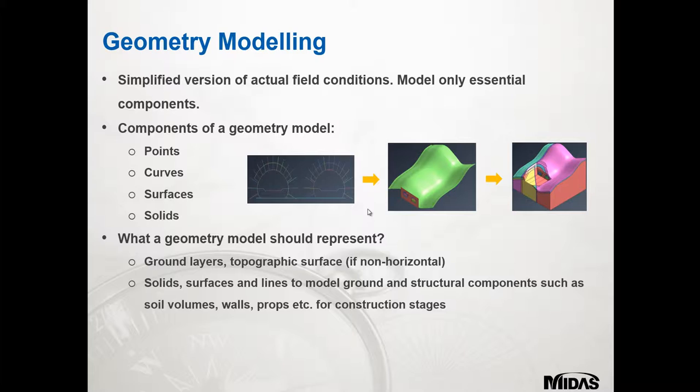So just going through the geometry modelling, it's a simplified version of actual field conditions. If you are carrying it out, you don't really want to overcomplicate things by adding parts that are not existing, like extractor fans and things like that. You just want to add the model, the liner of the tunnel and the rock bolts, which are displayed in this geometry. For any interconnections and things like that, it can become more complicated, but it's down to the designer to select what surfaces or what modelling he actually wants to carry out within the 3D model that he's created within GTS or any other program.